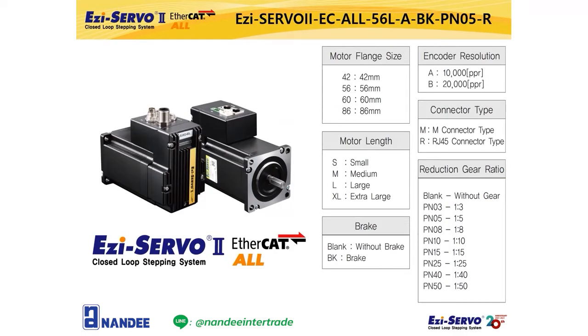In the example model name, EC means the product using the EtherCAT network, and All means an all-in-one product that combines a motor, a high-resolution encoder, a drive and EtherCAT network. 56 means 56 mm motor flange size, and L means motor length. A means a product with 10,000 ppr encoder applied. BK means that a brake is attached on the motor, and PN05 means that a planetary gearbox is attached on the motor.